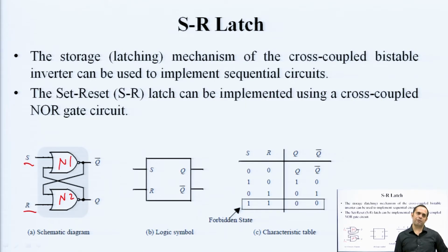Every flip flop and latch circuit generally gives you both the output and its complemented form. This is the symbol: you have two inputs S and R, and two outputs Q and Q bar. Just note that I have not added any clock or enable symbol as yet. There is no pin showing a clock or enabling point. I am just showing you the latching operation right now, so whatever you have at the input, how it is being altered at the output.